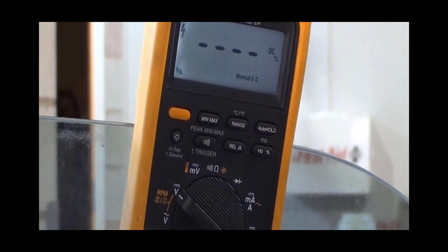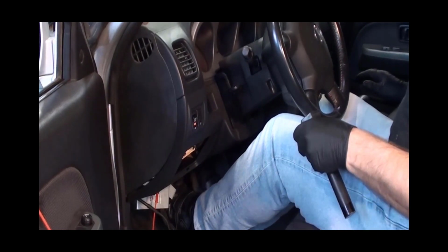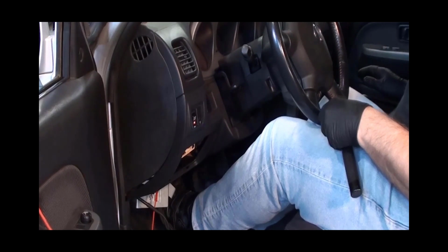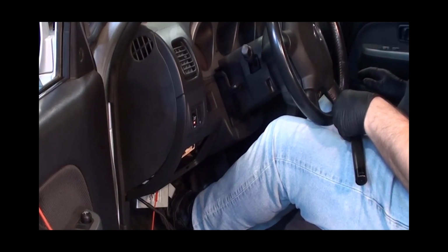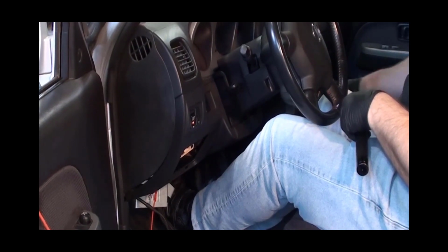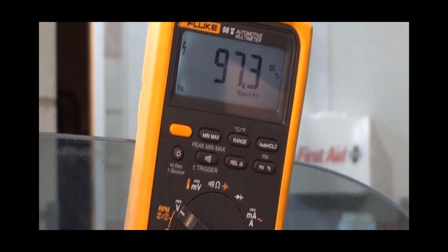With the engine running, set the parking brake. Place your foot on the brake pedal and press down hard. Shift into drive and fluctuate up and down on the gas pedal with your other foot. This should trigger the computer to adjust the duty cycle to accommodate for a simulated load from fluctuating the gas pedal while in drive. Observe the meter during the gas pedal fluctuation.